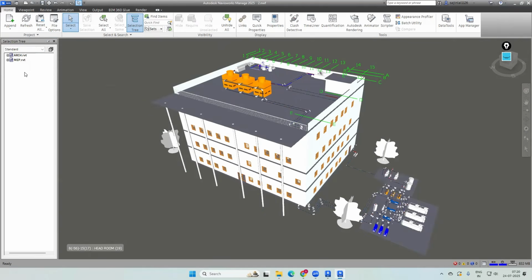Okay, appending will be adding like a new file. Whether that is Navisworks NWC, RVT, whatever it may be, it will be coming like a new file, and the refreshing option, switch back option, everything is possible in the appending option. But merging will be combining all the files, and there is no refresh, no switch back. File size will be bigger, and any updation, because parallelly if there are any changes happening in the other models that you have attached, for example, a Revit model, if I am doing something in the Revit, those updations, refresh, nothing will come in the merge option, but all those options will be available in the append. For simple real-time working, you have to append it.